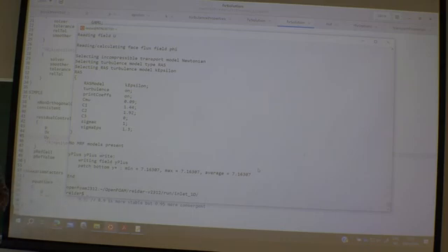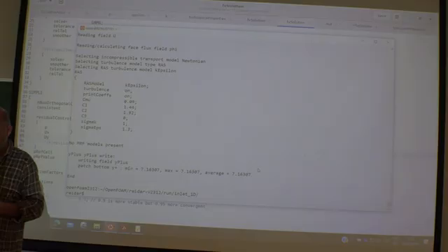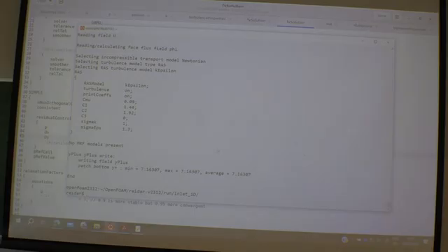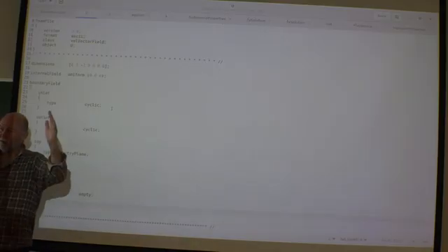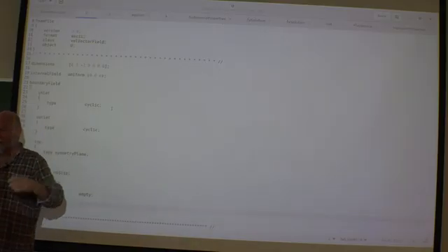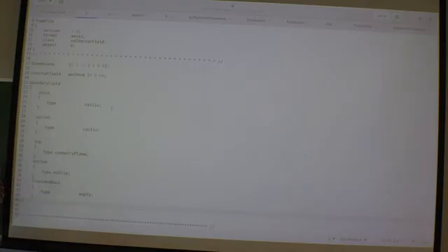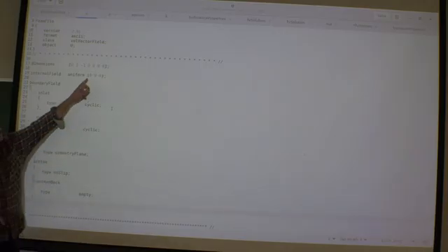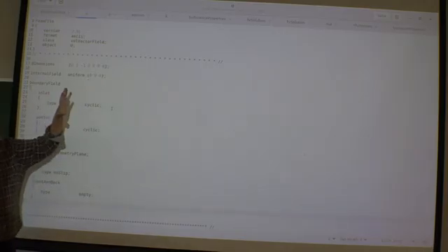I have another one. Yeah? Instead of the FV options, could you just put an internal field of 1, 0, 0 in the U file, and then let the cyclic boundary conditions do the job? No. That's a sad thing. I mean, here you have to specify cyclic because you want a fully developed profile at each side. Yeah, but that meant the uniform internal field at the top. Here, no, but this is just sort of the initial values.